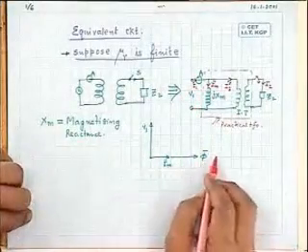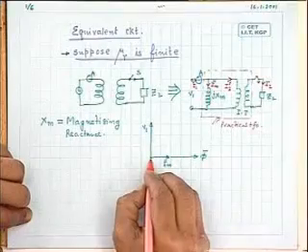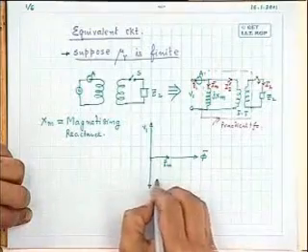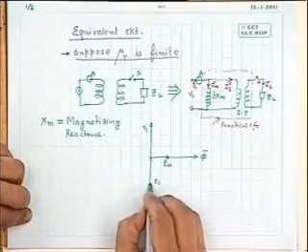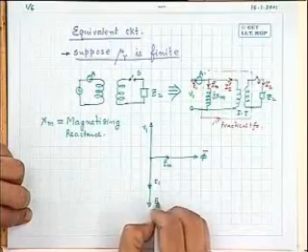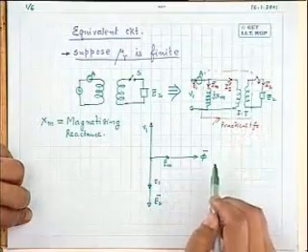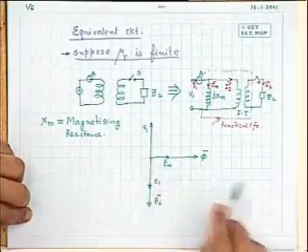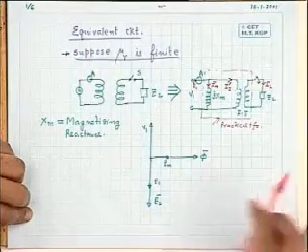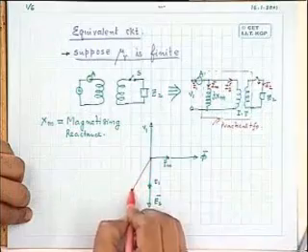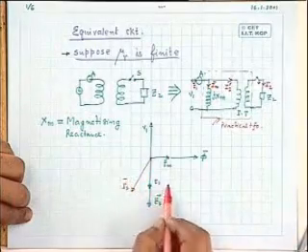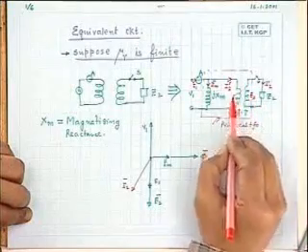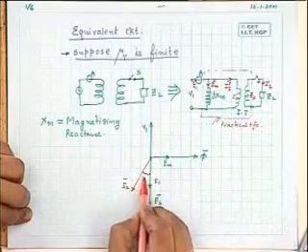So how will the phasor diagram now get modified? This is the phi. The induced voltages on the secondary and primary sides will be E1 and then E2. Suppose it is a stepped up transformer, and the secondary load is inductive in nature, say an RL load. Then the secondary current will be your I2. The angle by which it lags this voltage E2, remember this is E2, this is E1, will depend upon the power factor of the load, theta 2.